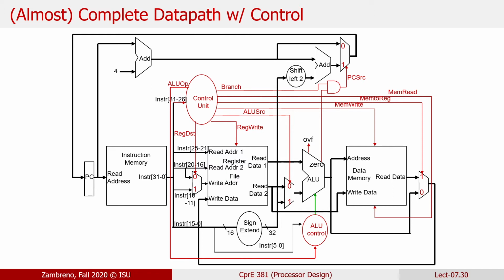So you would need a reset pin on that register for the program counter. It does turn out to be the case, though, that as we talk about the MIPS ABI and what kind of standard conventions there are for things like memory layout, there is an assumed starting initialization point for the program counter. And so at some point in project part B, you're going to want to initialize the program counter to that value. I think it's 40 million hex. I don't remember the exact value there. It doesn't change our implementation because we don't have nearly that much memory anyway.